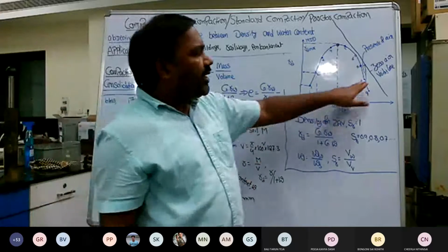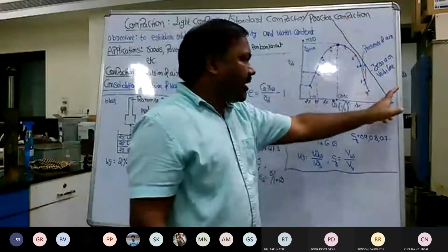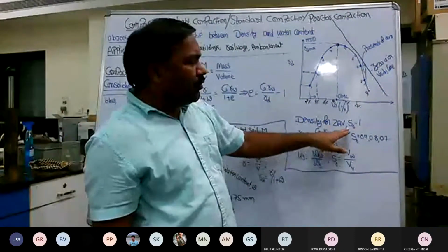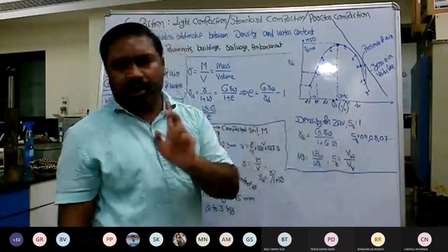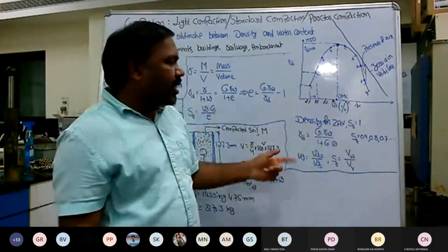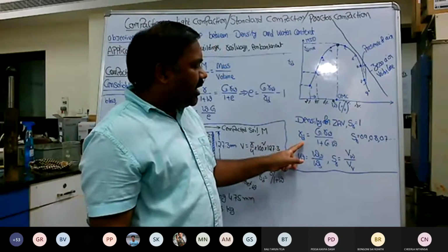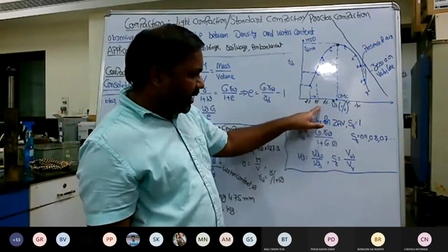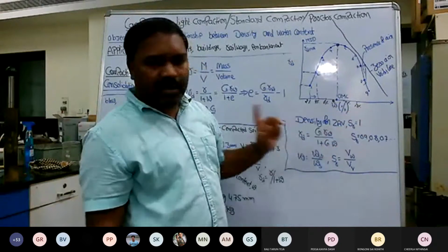Now, to make a small understanding, suppose you draw the zero air voids line. How do you draw it? For drawing the zero air voids line, you first assume that the degree of saturation is 1. Assuming Sr equals 1, keep on calculating gamma D for the decided water content values.